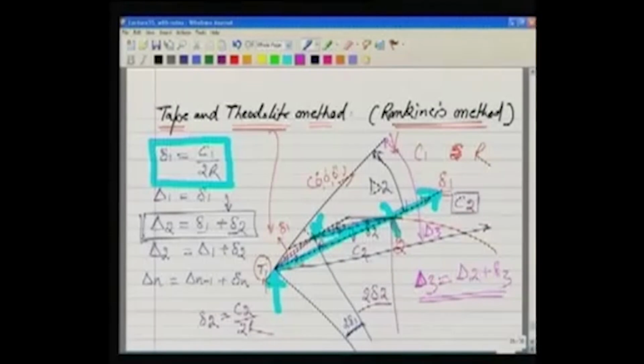So we know that we have to look in this direction, and then how much we will cut from here? From the point B, because there is someone who is standing at point B over here, he will cut a distance in this direction, which is equal to this particular chord. Well, we can say this chord to be C3. Generally all the chords will be same.